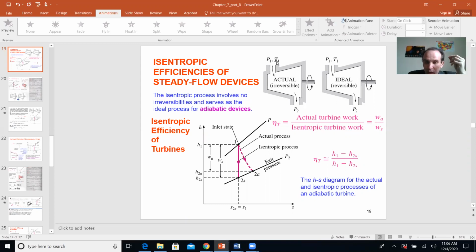So what happens? You have state one at the inlet, but you actually have two states two: the actual state two, and the hypothetical state two, how it would be if your device was isentropic. So they're different. Pressures in these states are the same, but they're different. Some people say pressure is the same but temperature is different. That is the convention, because the performance of your turbine or compressor is measured by pressure, right? So basically, you want your ideal device to reproduce the real one. You have state one and two states two, actual and hypothetical, and you solve the problem like before.